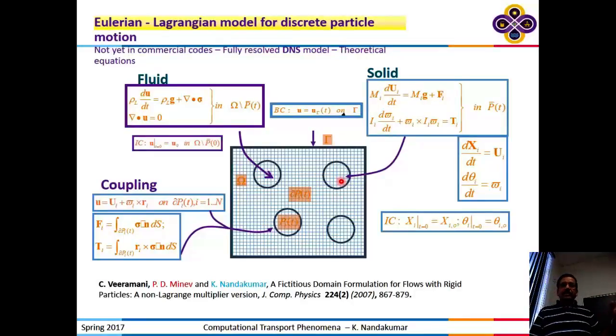Other than that, if you have collision between these particles, then you need to look at the material properties even in the DEM framework, because there will be an elastic rebound, right? So you need Young's modulus and all those properties of the particles. And if you're doing wear calculation, where you're interested in predicting how much a material is eroding due to this impact, then you need models that capture the impact velocity, impact angle, loss of material, etc. But CFD provides a general framework for tracking these particles and trying to identify where these erosions may occur.